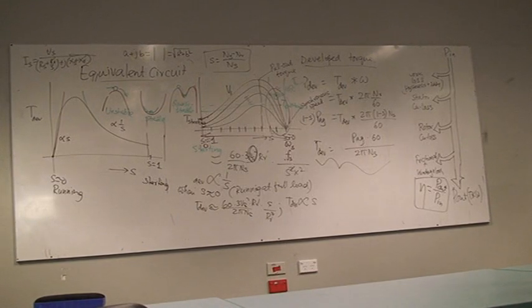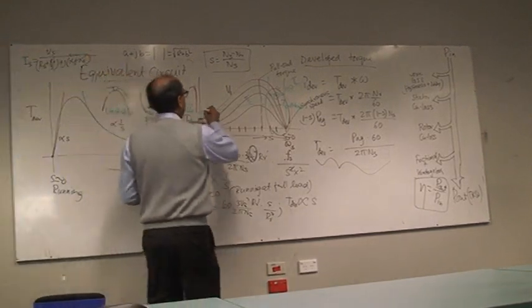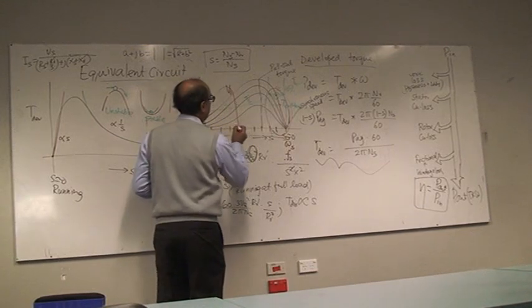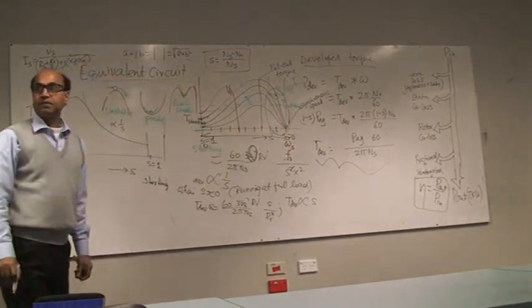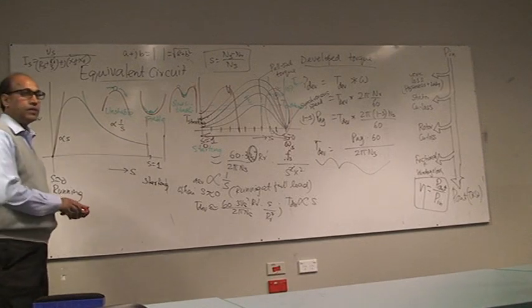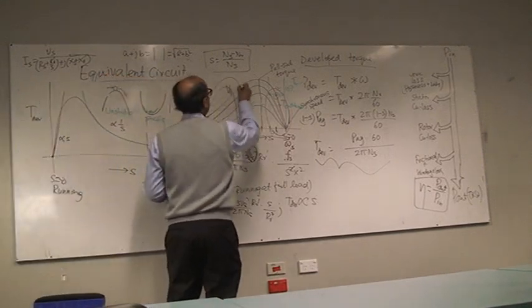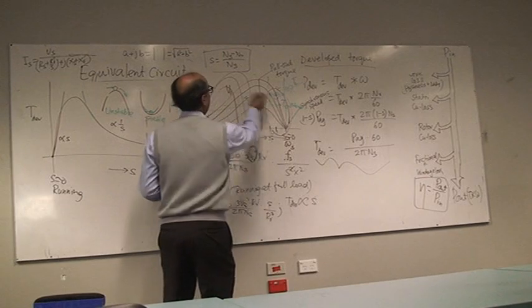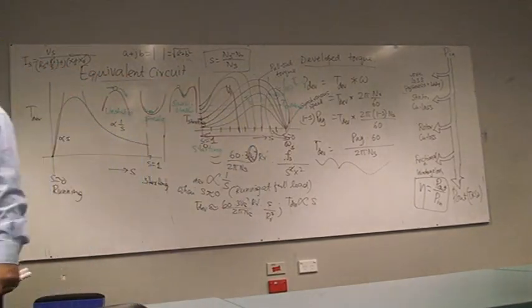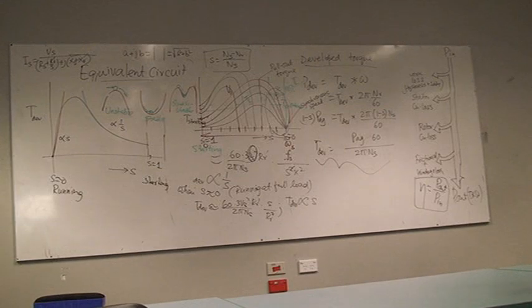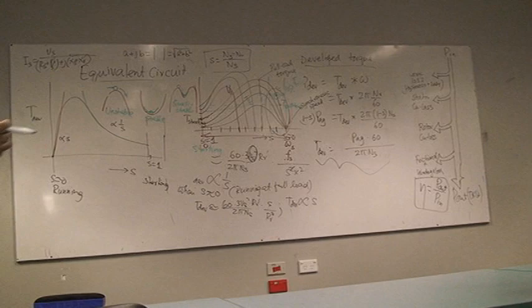So let's say you took the frequency of half Fs in that diagram. Would that curve shift, or would it just be a different point on the curve? So suppose you have half, you will get the characteristics like that. Yeah, so the curve actually shrinks down. Depending on your speed, you can get different frequency, you can get different characteristics. So that was the method we use, and we need an inverter to make that happen.